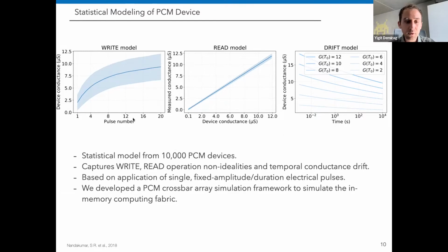What we are going to do is create a circuitry where each synapse consists of 2 of these devices. So you have 2 memristive devices. Whenever I want to increase the conductance of this synapse, I will send a single pulse to this device, so its conductance will increase. But this is just a positive number, right?